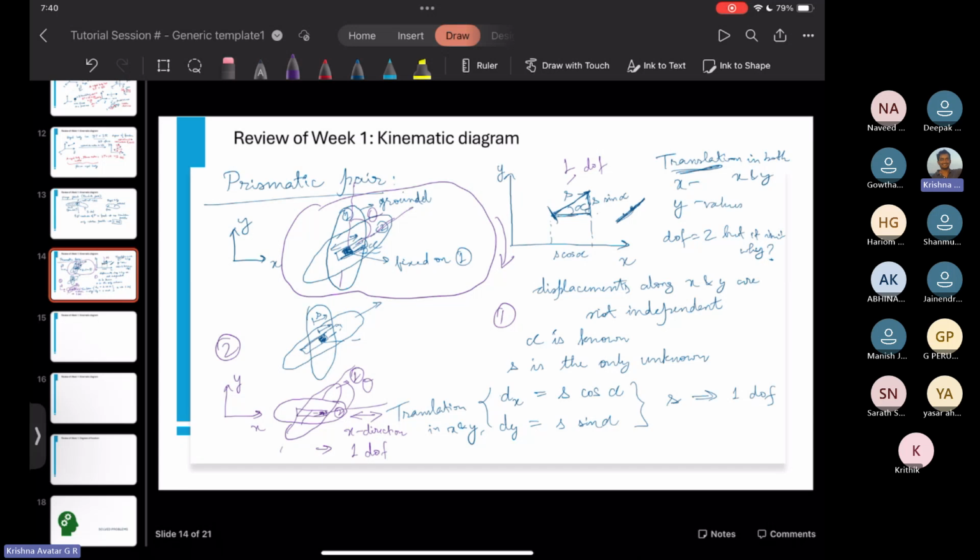Till the time we do not interfere with relative motion, we can do whatever we want with the mechanism. We can rotate the entire mechanism, or move it from one place to another. It's just that the relative motion should not be affected. And we are able to clearly see how we determine the degree of freedom for a prismatic pair. In this example it's prismatic, but for a general case, that's how we are able to do it.